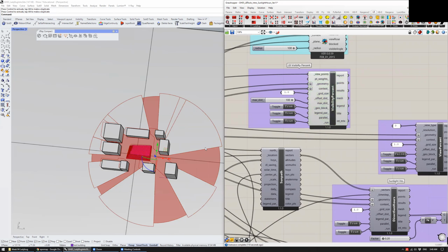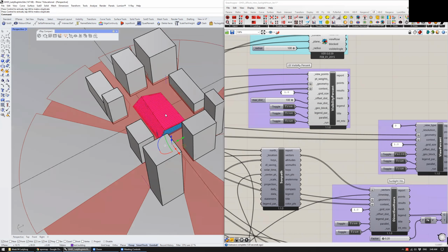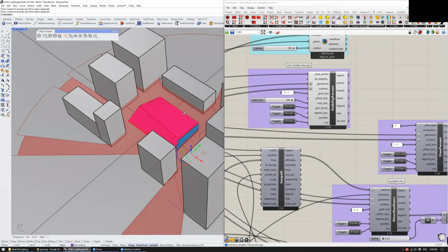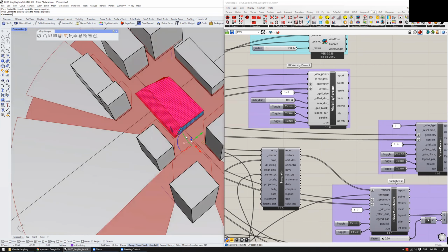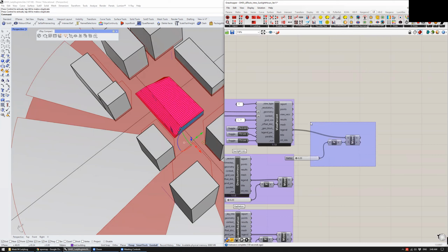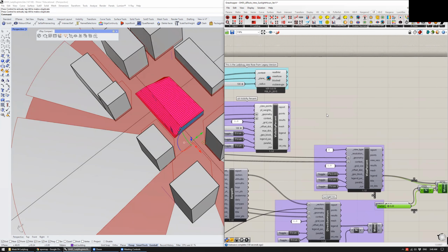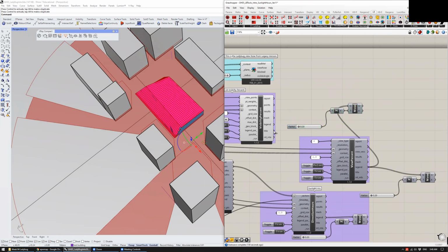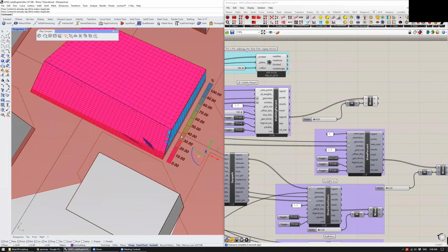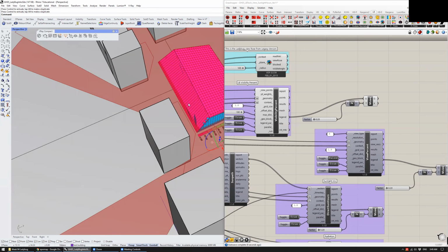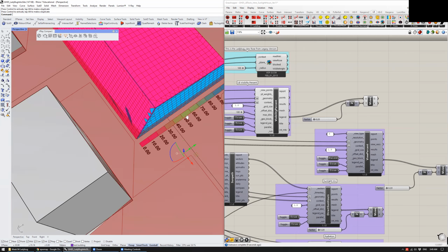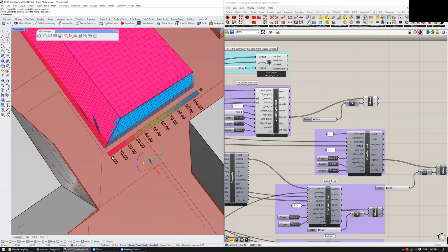I'll turn it on. What it does that's interesting is that it pairs with this. It uses the viewpoint and shoots rays out from it. Let me bring the legend in as well. Copy it over and move this over. In terms of percentage, it calculates how much of this is visible from that point. All this red stuff is invisible, or not seen, when you're standing here. This front face is 100%, that's what you see.